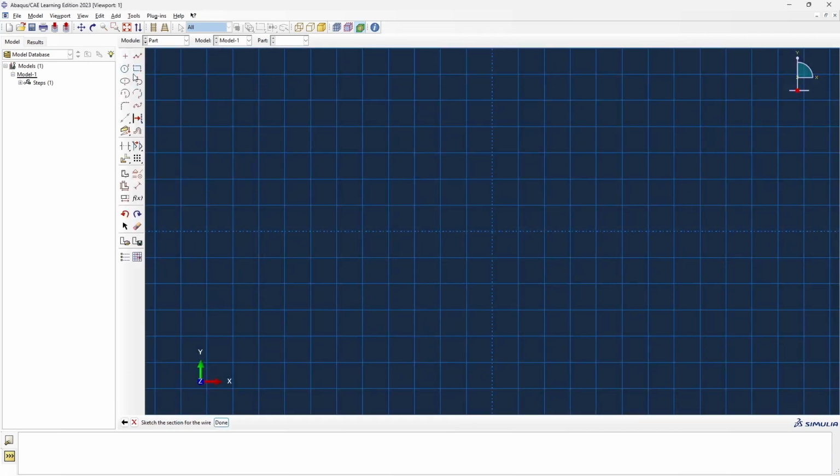So how do you create a hexagon? Well, there are multiple ways, but a way that I like is by creating a circle first. You can see the mini toolbar has a bunch of things. So in the first column, second row, you see something called create circle. So you hop into the origin. You can see from the dotted line intersection point, and you draw a circle of 10 units. You see what I did there? I said 10 units, and I did not say 10 centimeters or 10 meters, because right now, let's just draw the circles.